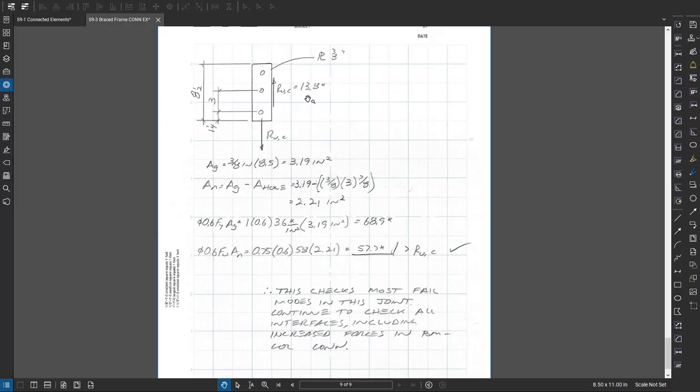So at the end of the day, my connection just in shear is quite a bit stronger than my demand. Whatever nuances I might be off by not looking at the 2-directional components, I'm not really worried about it given how much shear strength I have. I could similarly do that in tension, although those numbers would come out higher than this one. That's why I chose the shear.